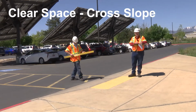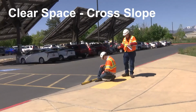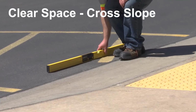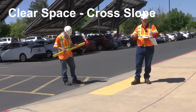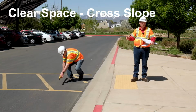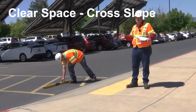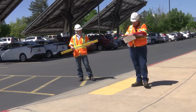So next on our item is the cross slope. We'll measure the cross slope of the clear space. We'll measure once in the gutter here, and we have 0.1, and then we'll also measure in the road, and we have 0.4. So which one do we put? 0.1 or 0.4? We'll put the higher of the 2, so we'll put 0.4. And where this is a mid-block crossing, we have the option of going up to the road grade. So we can take a measurement of the road grade to see what our maximum value is. Our road grade comes in as 0.4. So what do we do in the instance where we're less than 2%? We can go up to the 2%. Our 0.4 is less than 2%, so we pass.